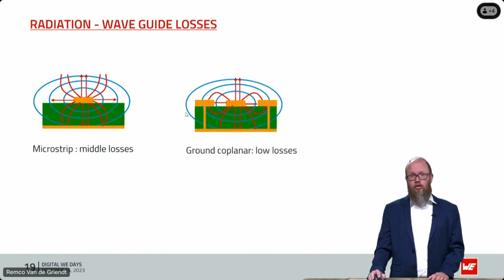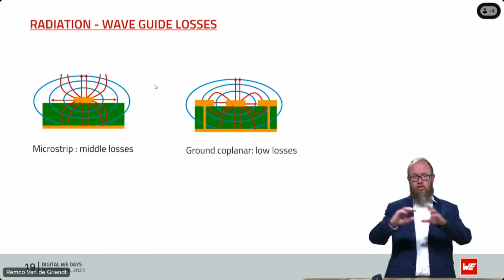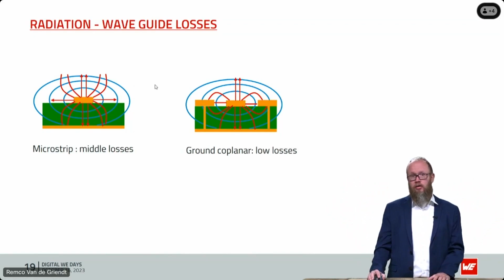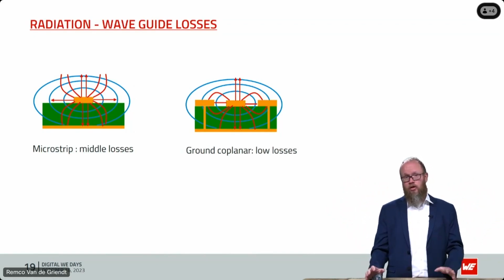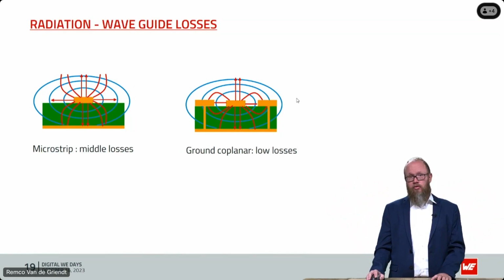If we do a ground opener that way, you see that here the electrical field is coupling into the ground part of the ground opener. And if you are also using vias as a sort of via fence, you also have a low impedance coupling to the ground plane. So you really have a good one. Then you really can couple everything of an electrical field into the PCB. So it's not going to spread out. So less interference like that, lower EMI problems maybe for the future. So that's a good one. Still, you can see, of course, here the magnetic field.